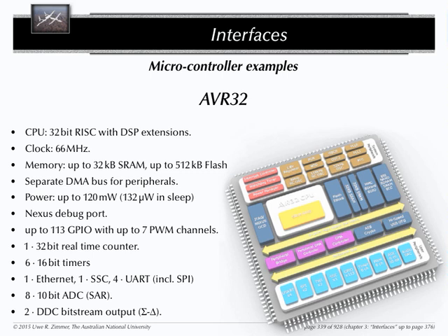The 10-bit ADC could be a bit better resolved than 10-bit, but this is all that AVR gave you on that one. But therefore, you actually have 8 physical converters. That's not too bad. And bitstream output, sigma delta converter. This is your digital to digital converter, which I introduced in the context of sigma delta converters. Yes, you actually have digital to digital converters here to produce bitstream outputs. The AVR32 is quite frequently used in audio processing environments, so hence it needs that kind of bitstream interface anyway.